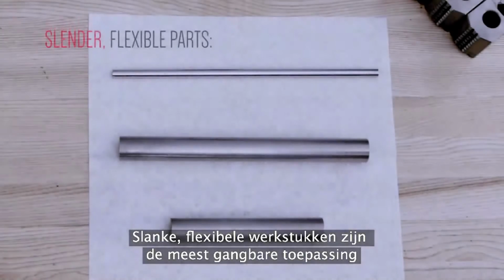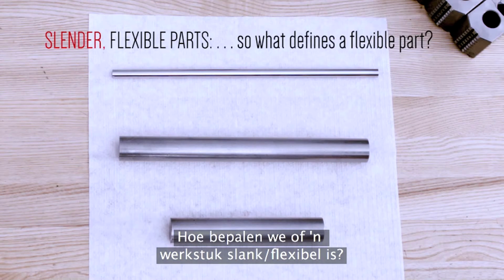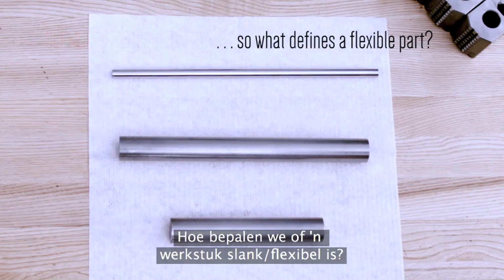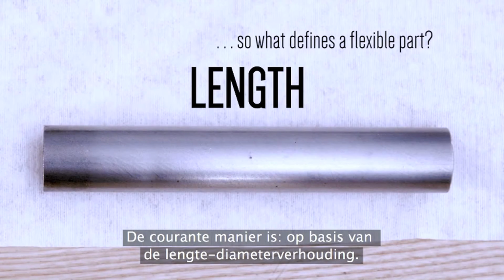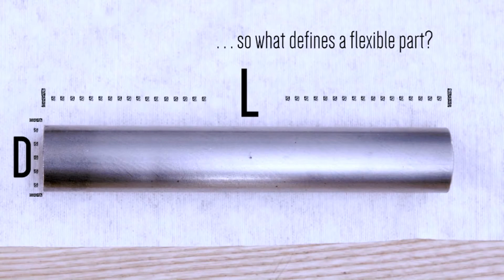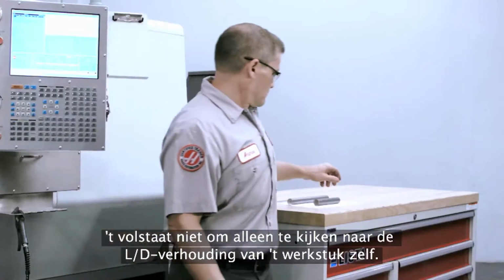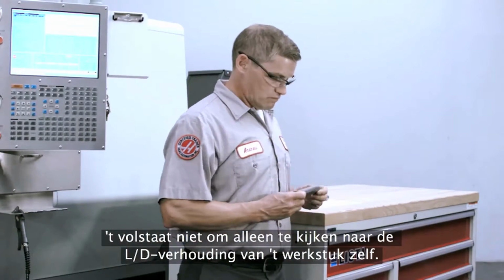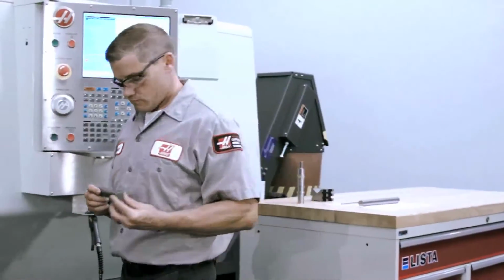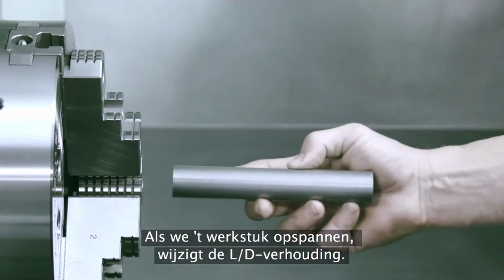Slender, flexible parts are probably the most common application where tailstock support is required. So what defines a slender, flexible part? The most common way is to refer to its length-to-diameter ratio, or L to D as it's often referred to. But let's be more specific. It really isn't enough just to look at the L to D ratio of the part by itself. When we grip the part, the effective L to D ratio changes.